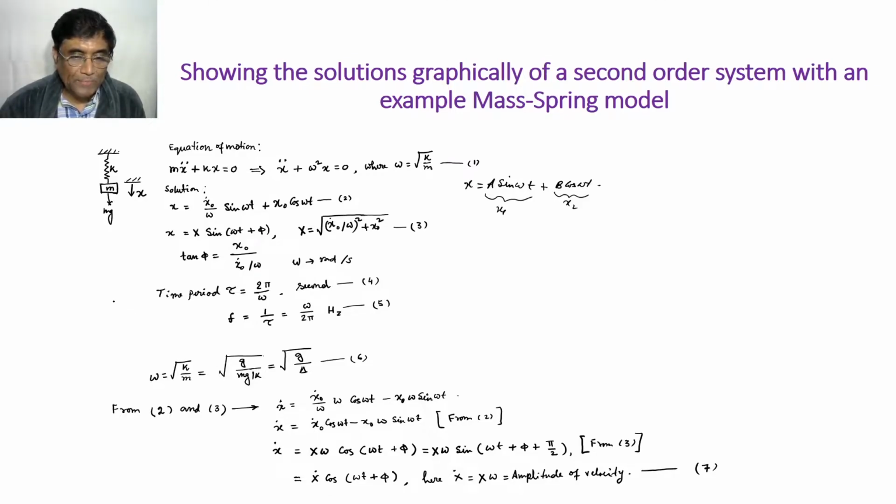So by definition, what is the stiffness of the spring? Force divided by deflection. Okay, so deflection equals force divided by k. Force is here mg, that is the force acting here. We are considering no other force, only gravity. So mg by k equals delta.